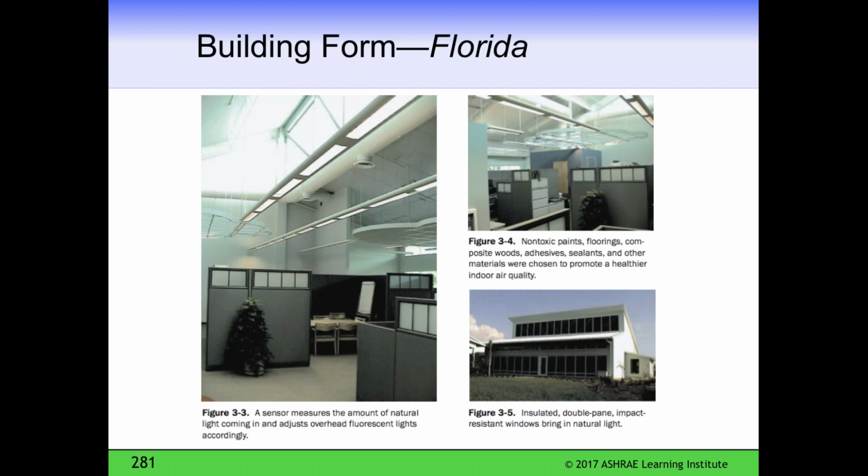So my rule of thumb, and it's been for some time now, 25 years at least, over a wide range of efficiency of lighting systems, is that when you have electric lighting in a space, and you're applying daylighting to that electric lighting, the daylighting will effectively let you reduce the lighting energy in that space by 50%. That seems to be what I see, and it's been around for a while.